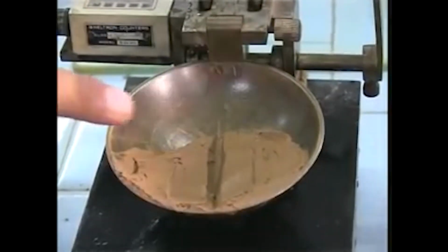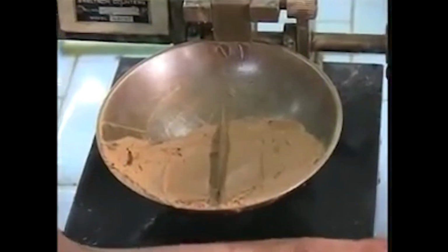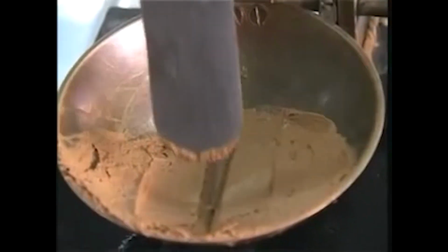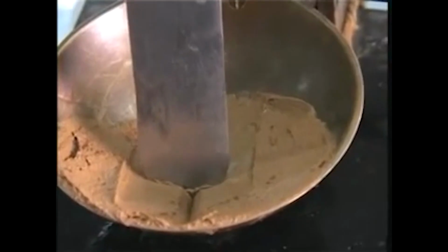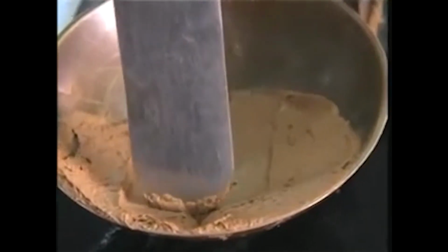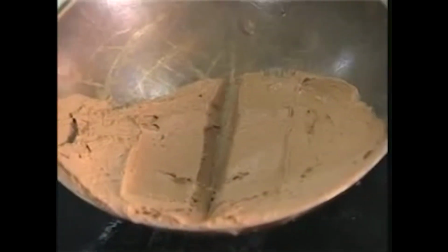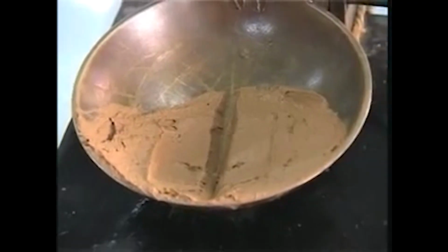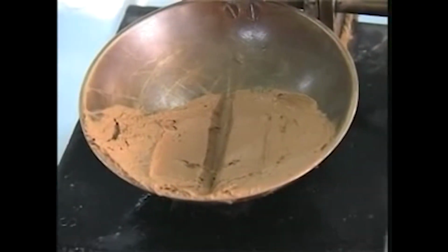And you see here the groove is closed by an amount of approximately 12.5 millimeter, and closure is approximately counted from there to about there, and the number of blows in this case is much larger than 25,